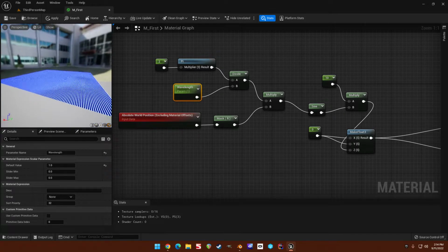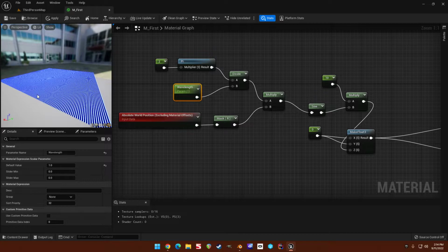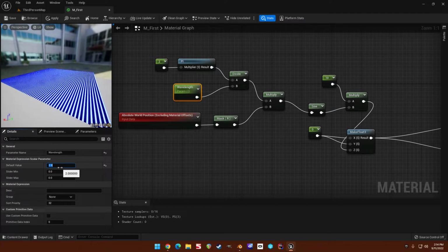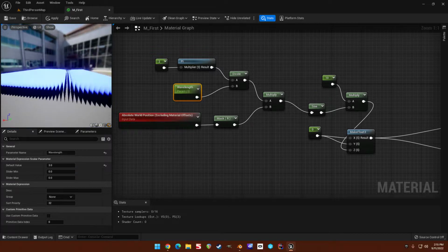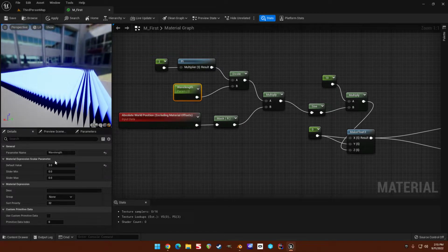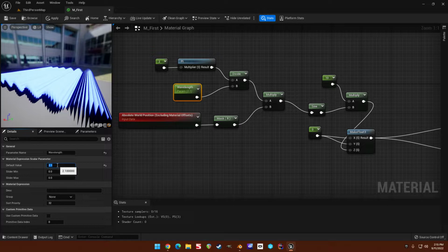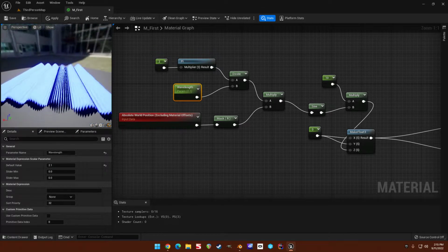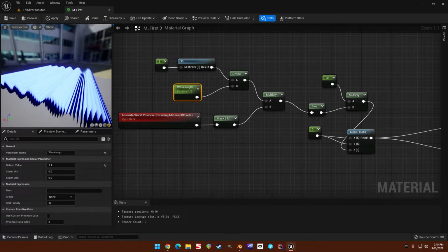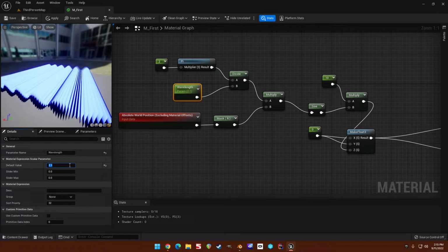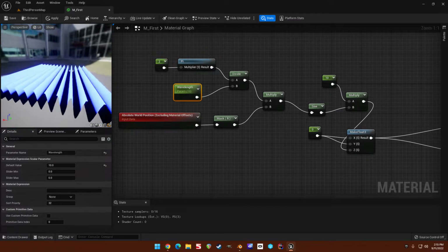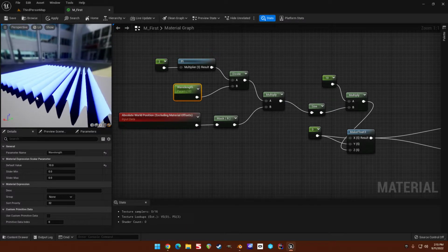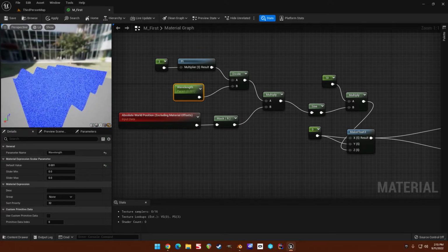This scientist named Nyquist figured out that it had to be a little more than 2 times. So you'll see 2 is not right, but 3 we can start representing. See? So maybe even 2.1. Let's see what 2.1 does. Yeah, it looks pretty aliased. It looks pretty messed up, right? This is because the wavelength is just too small, or the frequency is too high to be represented by that, right? So be careful when you start to do this, because at really low wavelengths we could get really bizarre results. See, look at that.